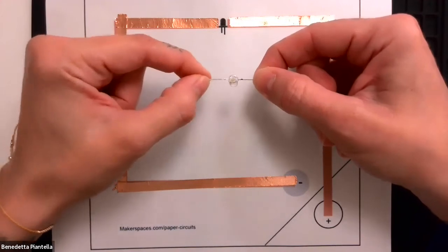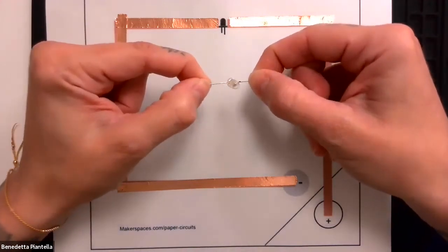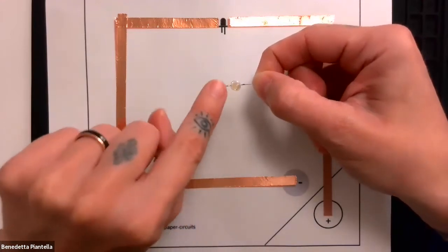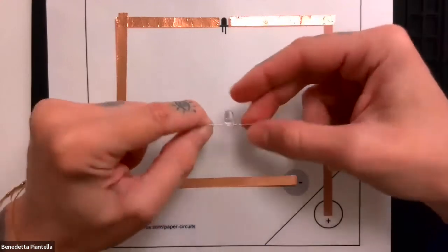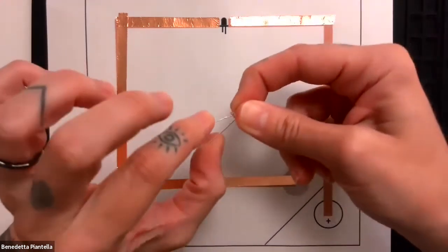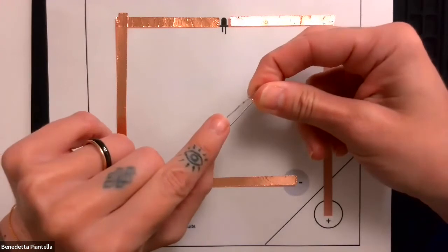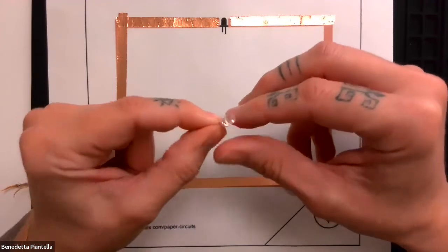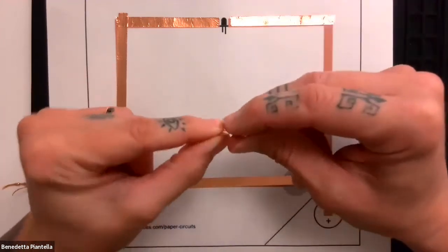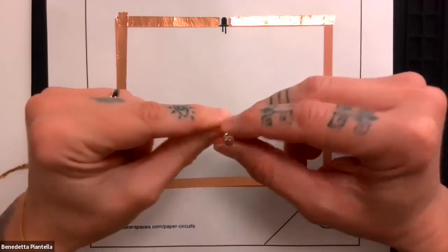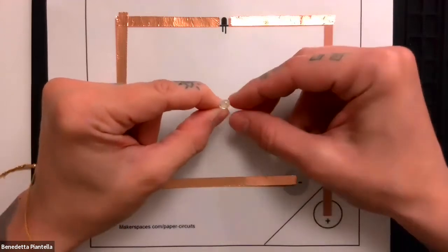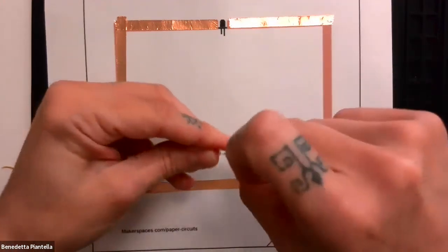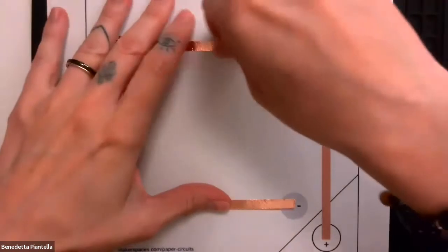Sometimes LEDs will actually also have another way to tell, which is that the enclosure at the top, usually the negative side, will have a little slit cut out of it. So if you accidentally shorten the leads and you forget which way you need to insert it in a circuit, you can usually look at the top and still make out the orientation of this component.